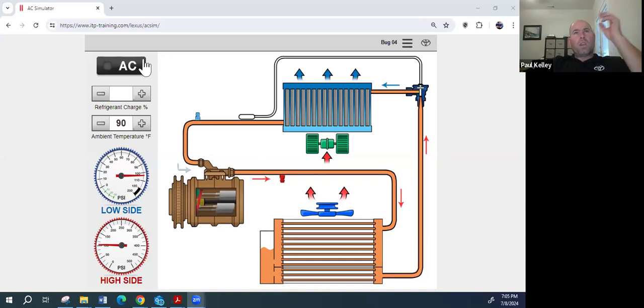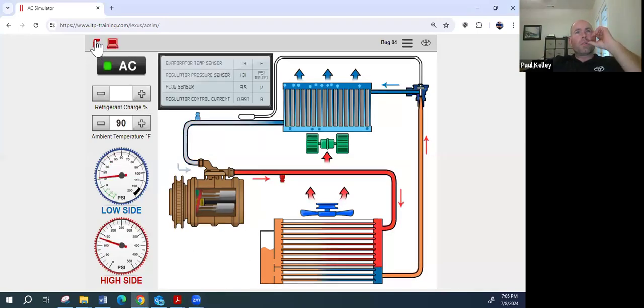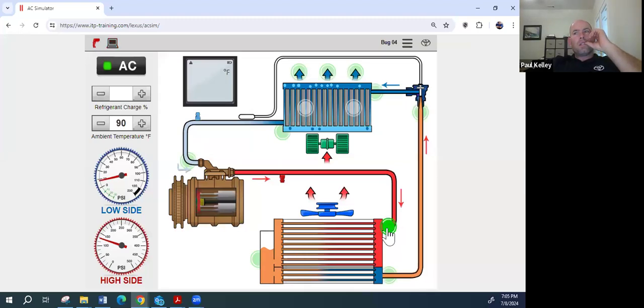All right, well, we can go ahead and run around like crazy with our temperature gun if you want. These seem reasonably good. We got a 110 there. Whoa, 5 degrees. I've never seen a 5. Anybody, we've never seen a 5 on an evaporator. That's kind of interesting. And there's a visual cue here. We're showing actually bubbles right here. It's kind of interesting.